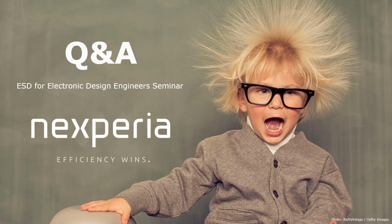Just a side comment on surge robustness, or especially ESD robustness, since we talked about the size of external ESD protection. In general, if you want a really robust ESD protection device, you have to spend some silicon area. And if you want high surge robustness, for example with the TVS portfolio we offer, then we also have to spend more silicon area.